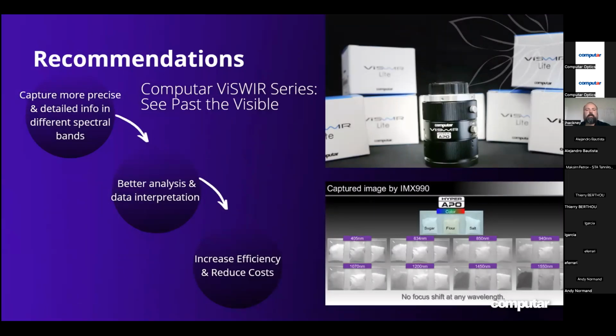So some recommendations. Let's talk about Computar's ViSWIR series. A high-quality lens like ViSWIR series can help capture more precise and detailed information in different spectral bands, leading to better analysis and interpretation of data. The ViSWIR series minimizes the focus shift within a few microns at a wide range of wavelengths by using ultra-low and low partial dispersion glass paired with superior design technology. With this, spectral imaging is achieved with a single camera solution by simply enhancing the lighting.